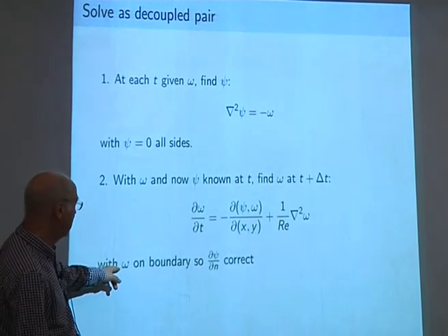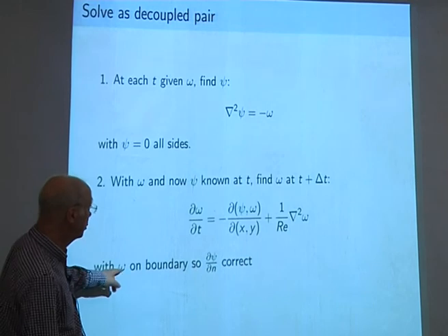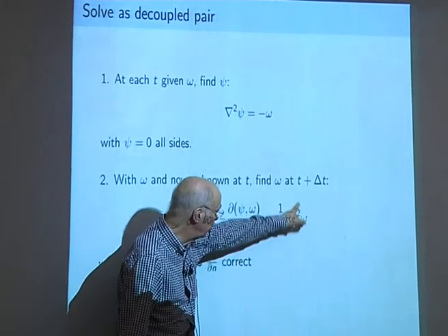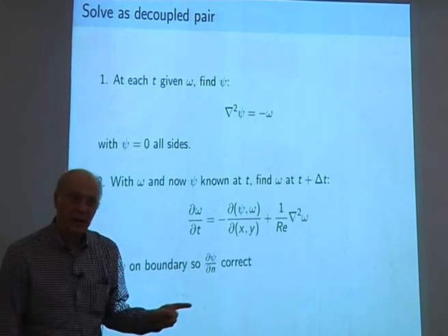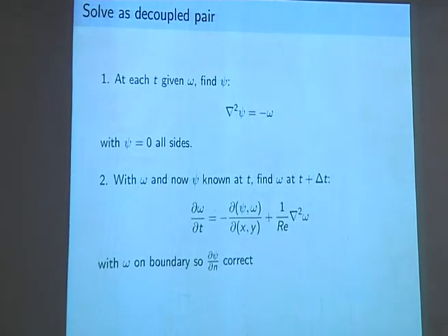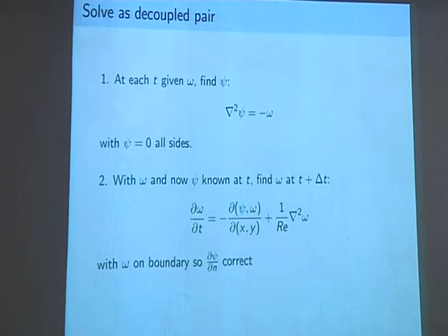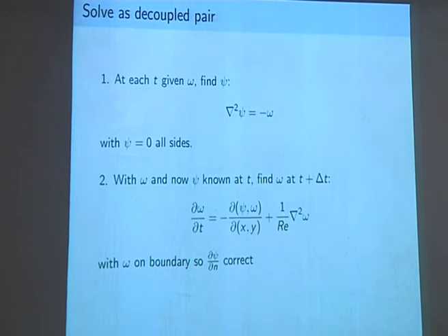And we just, please, can you give me some boundary conditions? Because of two spatial derivatives here, I need a boundary condition on the vorticity, and I don't have one. I have a second condition on the normal derivative of the stream function. So this means this problem is not quite decoupled.